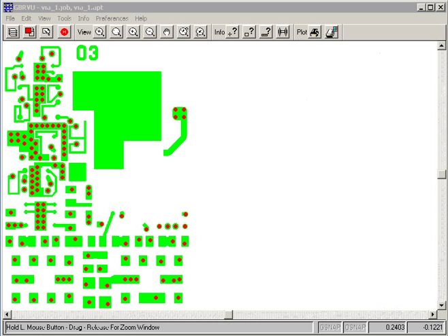So what you're looking at right now is the top Gerber file and the top drill file for this multi-layer board we're going to convert. You can see it's mostly plain areas, a few things that look like traces but actually are just plain areas, and a number of round pads, and then the vias are Gerber flashes.